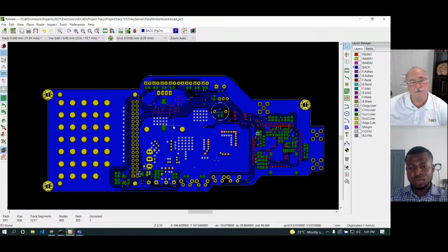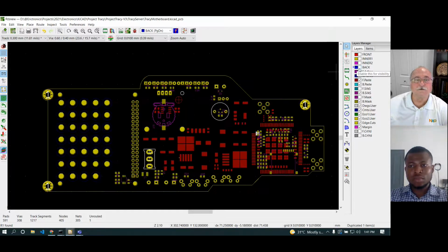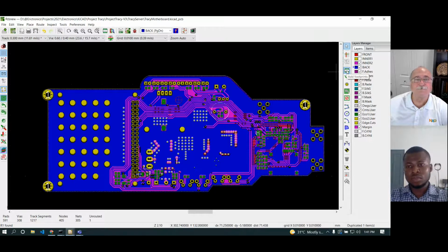So I call layer 4 an orphan layer, because except in the cases where you do have flood on adjacent layer 3, then you must route every signal, if possible, with coplanar ground traces or ground flood. So from this point, to show where Eric's been able to achieve that, to create good transmission lines on layer 4 because of the adjacent flooding, if you could put layer 3 on also at the same time, please. So 3 and 4 at the same time. Yeah, so I'm showing 3 and 4. Okay.